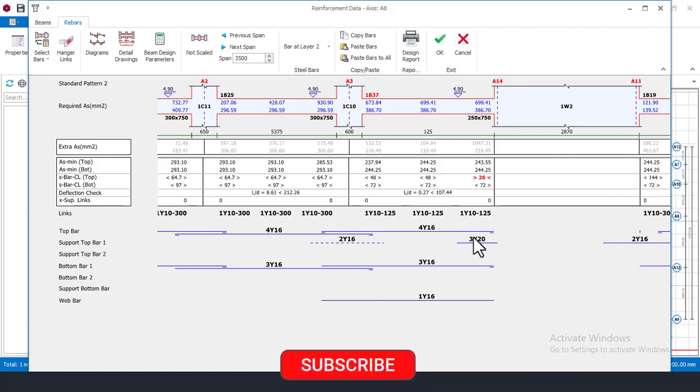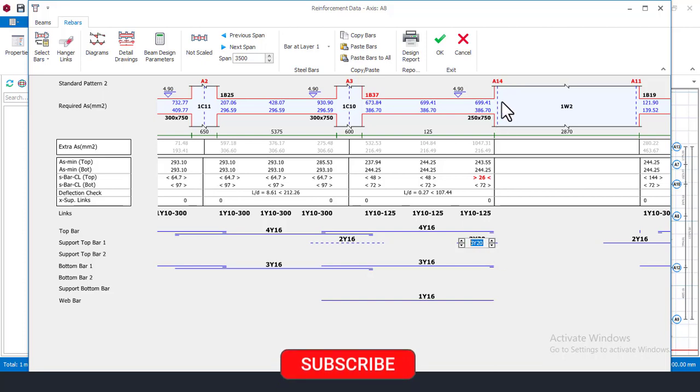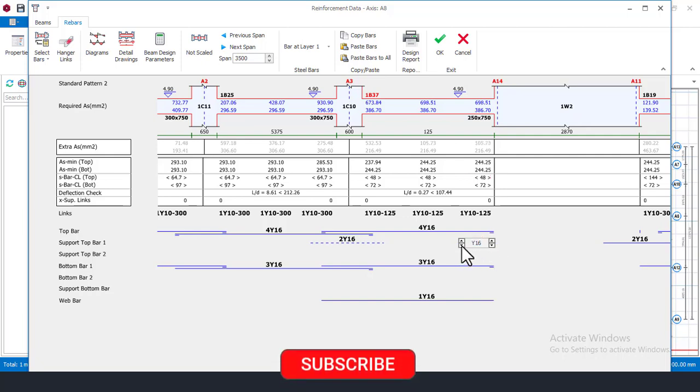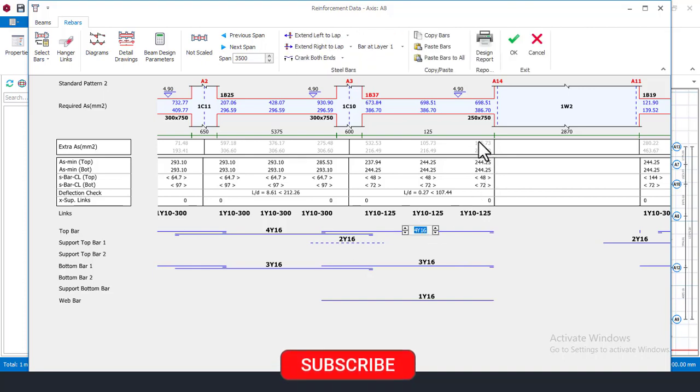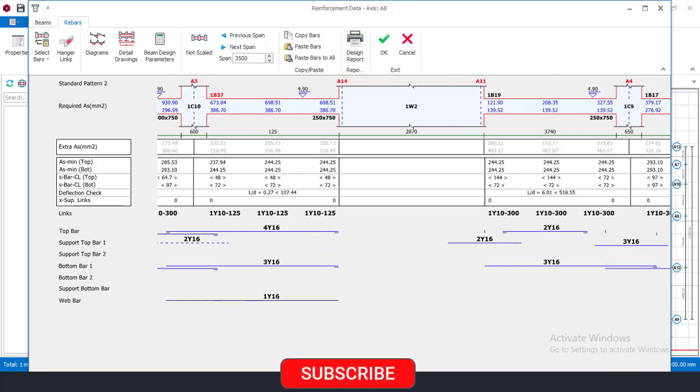Again, here right now, since there's a shear wall here, there's a wall here, you can see that this place we have much moment because of the contact between the beam, the wall and the beam. So I'll come here right now and then reduce this first to 16. Try to remove this entirely if that will be okay. Okay, that's fine. So this 4 was okay to carry that. That's right, there's no failure at the top here. Again, you can see why you are meant to check your design, because this software most times tries to over design. It tries to perform over design because what the software is considering is the safety of the structure.